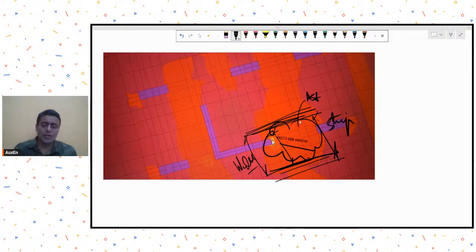So I think instead of directly relying on a FEM based output, it may be better to use the strip based approach where the internal averaging will be done by the SAFE software. Okay, and how to decide the strip width will usually depend on the type of structure that you have. So you will have to take a judgment call on the basis of the moment contours. You will be able to make a judgment on what your strip width should be. Okay.